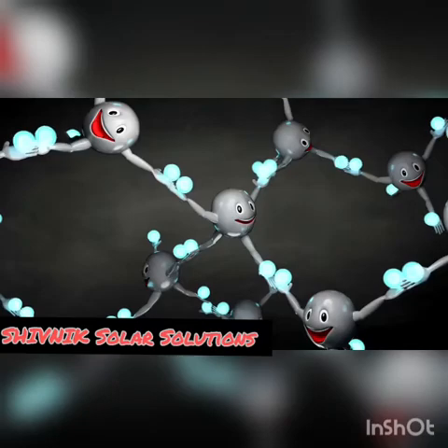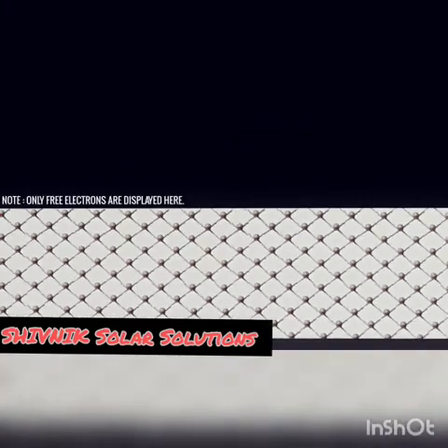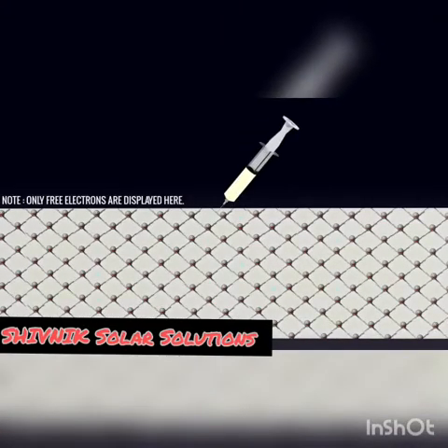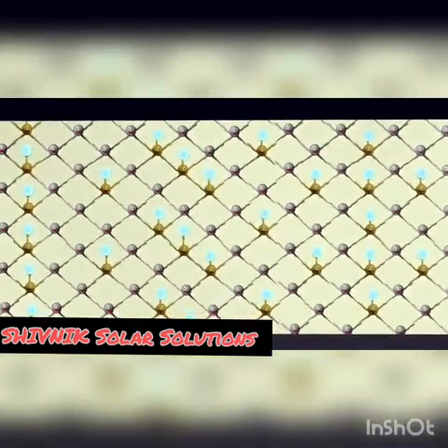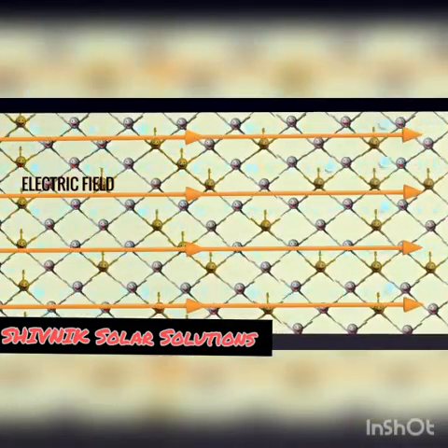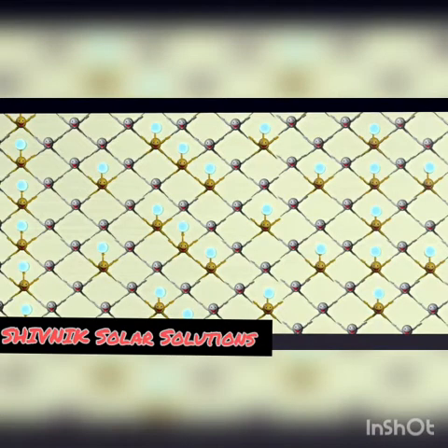To make the study easier, let's consider a 2D structure of the silicon crystals. Assume that phosphorus atoms with 5 valence electrons are injected into it. Here, one electron is free to move. In this structure, when the electrons get sufficient energy, they will move freely. Let's try to make a highly simplified solar cell using only this type of material.